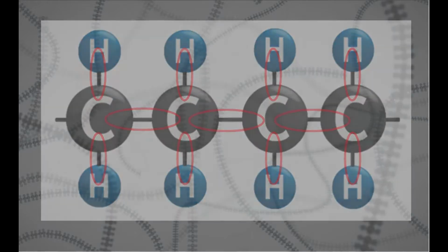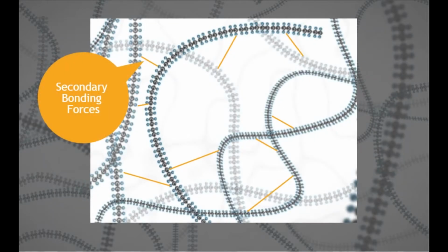In addition, there are secondary bonding forces present between the individual chains. Because these forces are about 100 times lower than the primary forces, they can be softened by applying heat, which lowers them further and allows the material or molecule chains to slide along each other to flow.